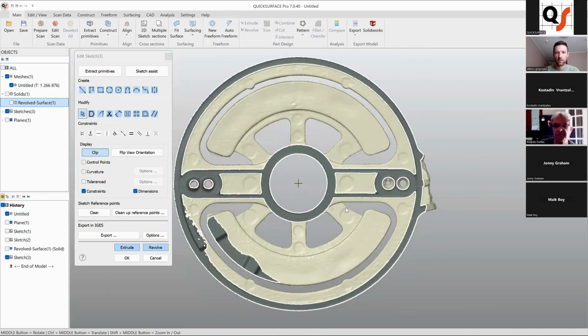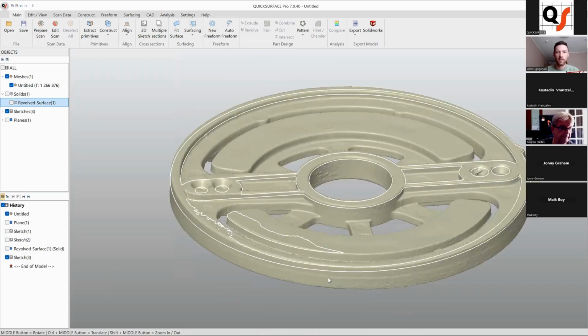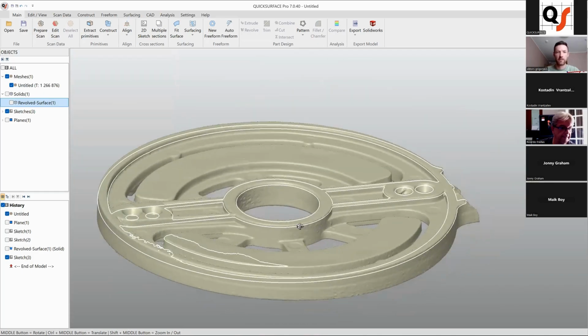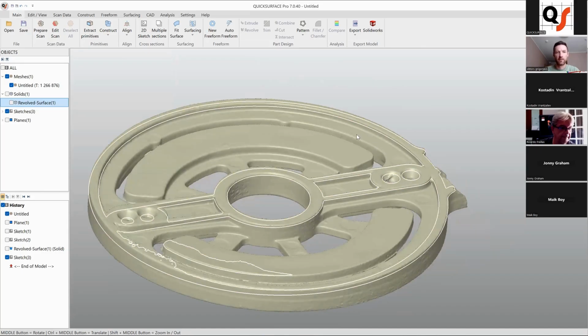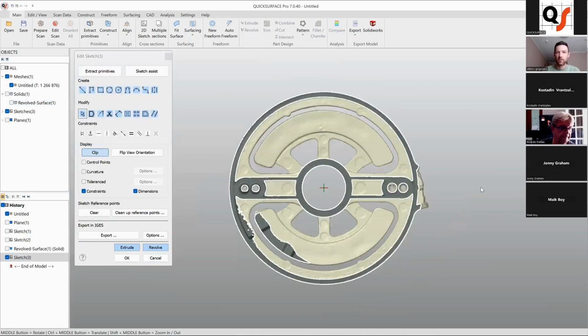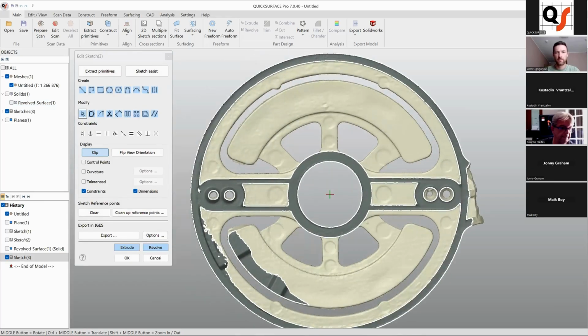And what I want to create right now is the first circular, cylindrical part, here if you need to see better. The cutter that will create this step right here. I'll go back to sketch. Typically you would select all these mesh points and fit some entity, but considering this part is warped, most likely the result is going to be different.